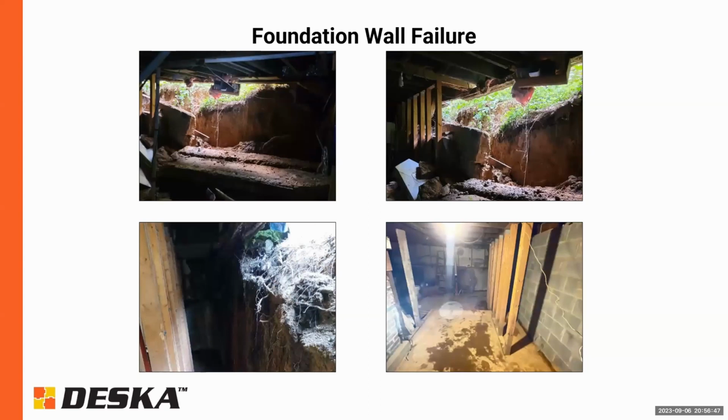Here's an example of a wall that had caved in completely. It was about 26 feet of wall actually, and most of the side of the home. This particularly was in North Arlington, and the wall was reinforced but had many cold joints in it, and there were several drainage issues on the outside. And fortunately, this homeowner actually had that cripple wall installed there. You can see in the top right corner, at some point to support a staircase, and that really is probably what saved the two-story home above it.